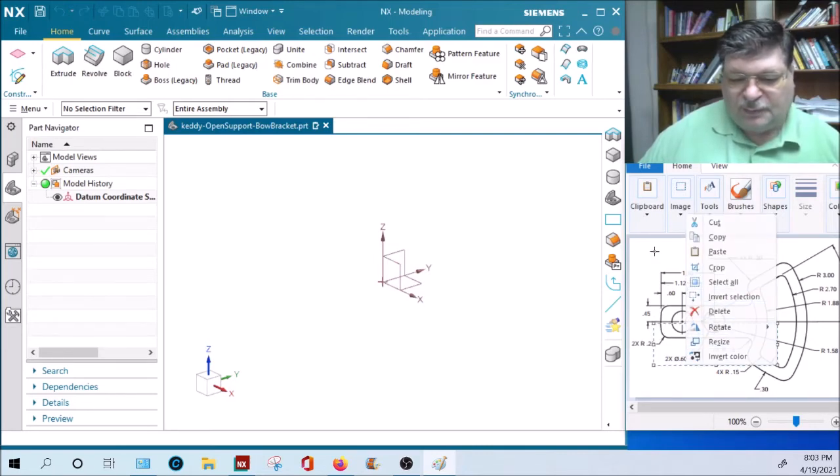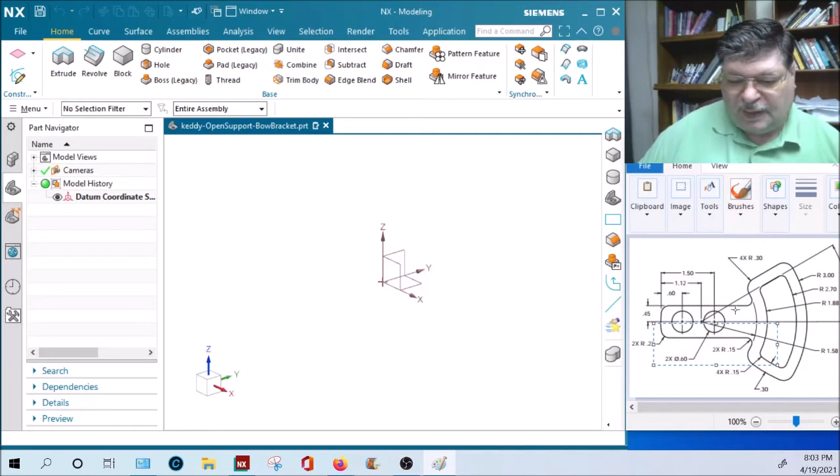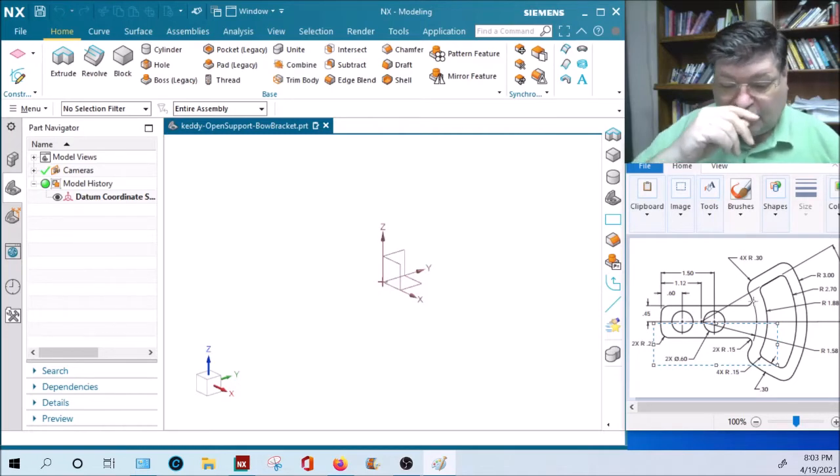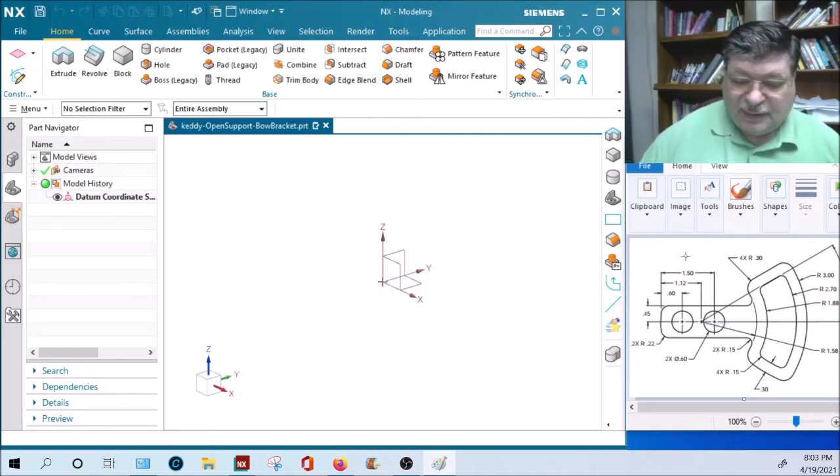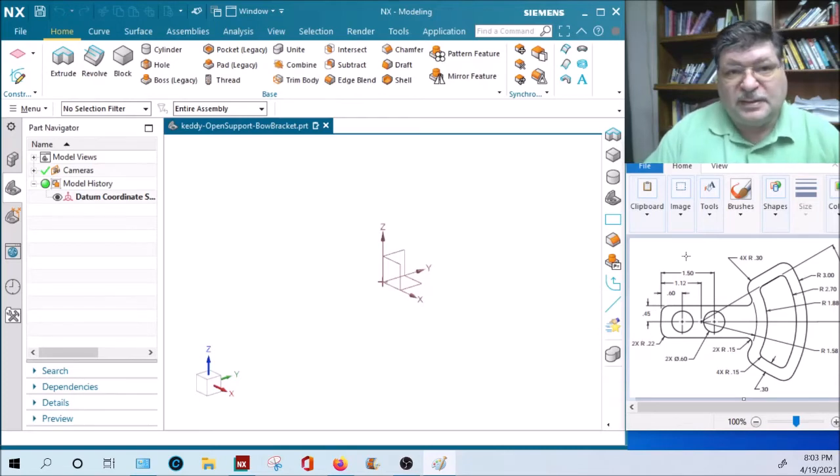Okay, if we count the number of lines in this sketch, the outer edge of the sketch, got a horizontal line, then an arc. So 1, 2, 3, 4, 5, 6, 7, 8, 9, 10, 11, 12, 13, 14, 15, 16 by my count. 16 lines. Now the problem with 16 lines, anytime a sketch gets over about 10 lines, I try to dumb it down because 10 lines takes a lot.